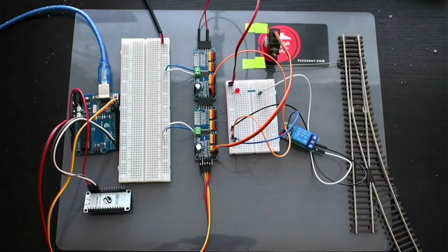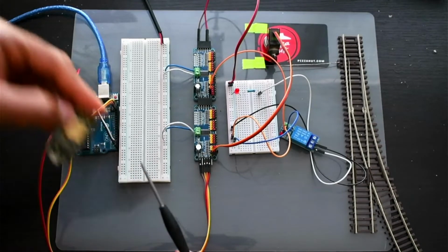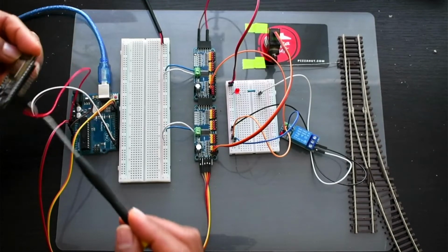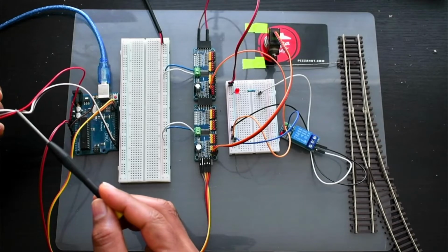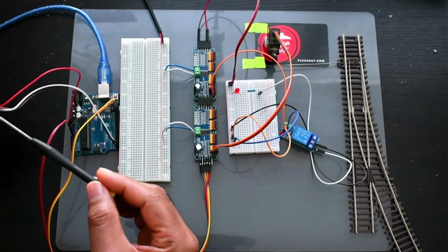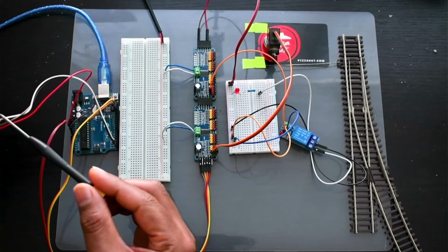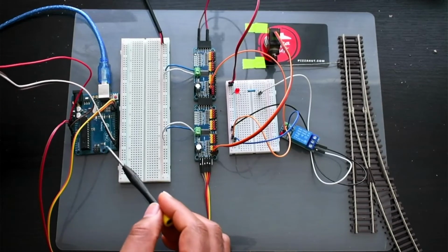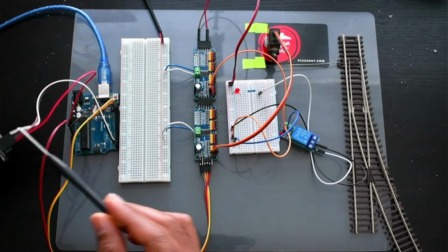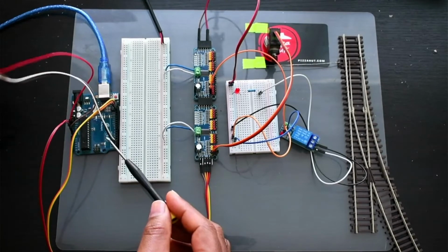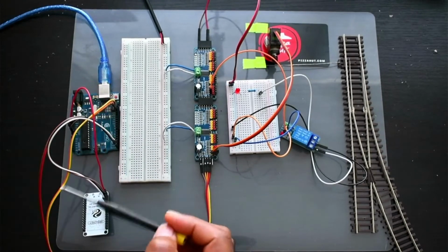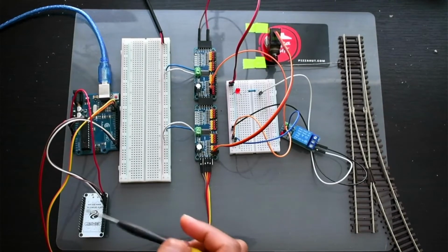So here now you can see I have done the configuration with all the boards. First thing you will see, this is a NodeMCU. From NodeMCU, this red one and ground one: red one is 3 volt VCC which is coming from Arduino, and ground one is GND. White one is RX and black one is TX, which go opposite. So RX from here will go to TX from here, and TX from here will go to RX from here. That is one configuration, from Arduino Uno to NodeMCU.